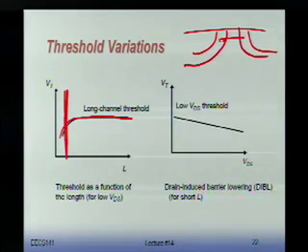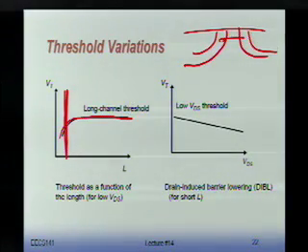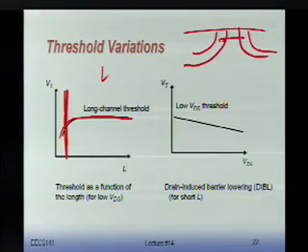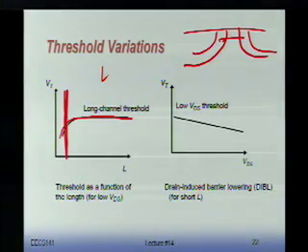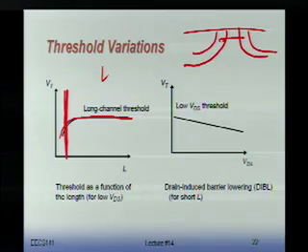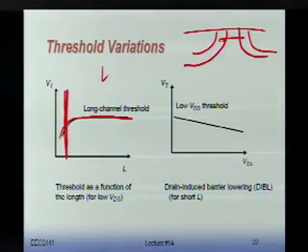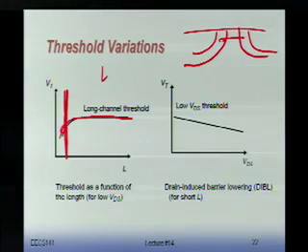Right, so typically digital designers like speed. They don't care about all of the other stuff. They like energy dissipation. So digital designers typically always use minimum size L. There's no reason to make a transistor with a longer L. While analog designers like to do all kinds of weird shapes of W's and L's, digital designers are very simplistic. They say, nope, every transistor, make it as fast as you can, make it as small capacitance as you can. So use minimum L. But that comes at a penalty because minimum L, as you can see, has somewhat of a lower threshold. It's good for performance. It's bad for leakage. So that's something you always see as well.